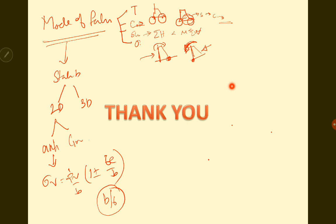In the graphical method, what you do is you just draw the outer middle third line and the inner middle third line and check if the resultant is well within this limit. That is the graphical method.